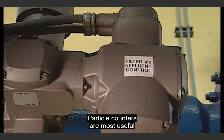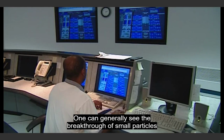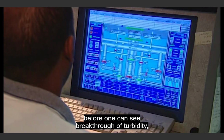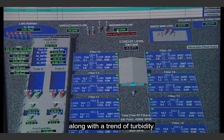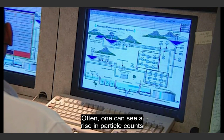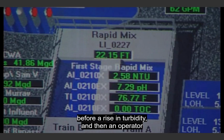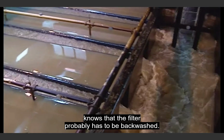Particle counters are most useful on the effluents of a filter. One can generally see the breakthrough of small particles before one can see breakthrough of turbidity. So often an operator will watch a trend of particle counts along with a trend of turbidity. Often one can see a rise in particle counts before a rise in turbidity, and then an operator knows that the filter probably has to be backwashed.